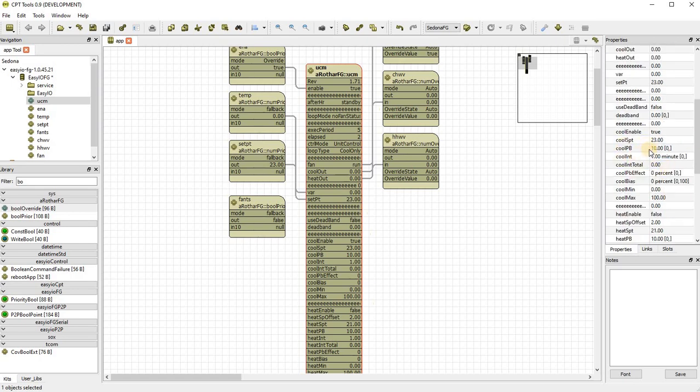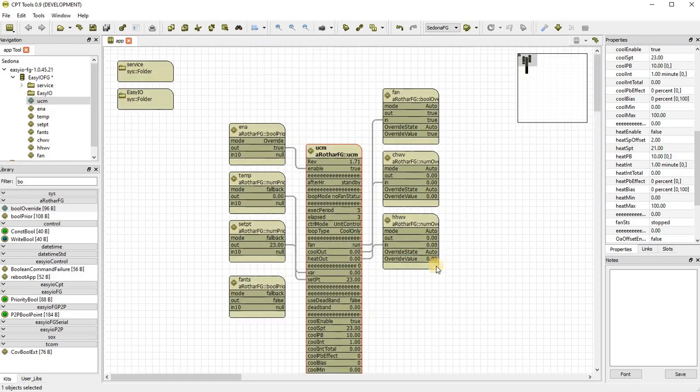This is the cooling loop configuration, the heating loop configuration, the fan status, the outside air offset enable, the unoccupied setback configuration, and our fire input as well as fan run hours. So the configuration has been broken up, and these E things just help focus your eye on the area rather than squishing it all together and making it difficult to see because, you know, there's so much of it.